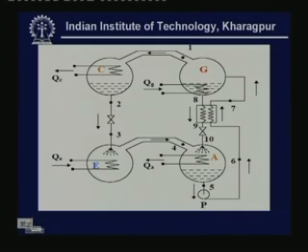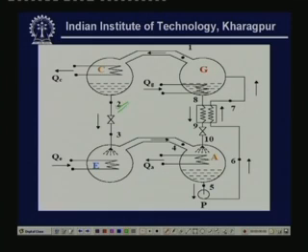Point 2, okay, point 2 is the refrigerant liquid at high pressure, saturated refrigerant liquid at high pressure, and it is at the exit of the condenser. Point 3 is a low pressure refrigerant at evaporator pressure, and point 4 is low temperature low pressure saturated vapor. Point 5 is weak solution at evaporator pressure.